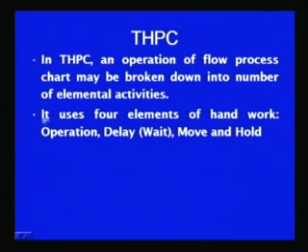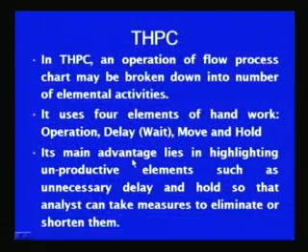Because the two hand process chart records things in greater detail, the significance of these elements is also different from that used in the flow process chart. The significance of operation, delay, move and hold will be covered in the coming slide. The main advantage of the two hand process chart is in highlighting the unproductive elements such as unnecessary delay and hold.